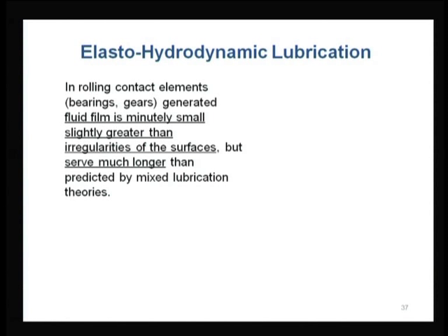Another domain, as I mentioned, between mixed lubrication and hydrodynamic lubrication comes elasto-hydrodynamic lubrication. So, a few lines are written over here. We say that in rolling contact elements, whatever the rolling action is happening, as we studied earlier, fatigue is the main wear phenomenon. In that case, what will happen? The fluid film will not be very high, the liquid lubricant film will not be dominating.